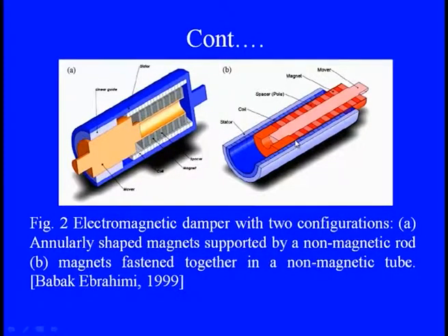So we have both things. We have the stator at the outer part; this is my stator. After that we have the coiled part. These coils are supporting our spacer, and the magnet part is coupled with the mover part. We can provide the electromagnetic field, and whenever kinetic energy comes into the system through the movement of the mover part, it can be absorbed using these magnets.